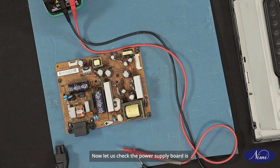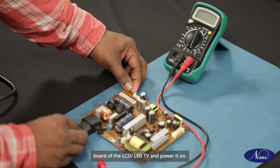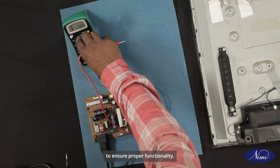Now let us check if the power supply board is working using a multimeter. So examine the description near the connector of the cable leading to the LCD or LED TV. Ensure that the voltage indicated matches the required specifications for the TV. The same voltage should be visible at the end of the cable when checked. Connect the AC socket to the power supply board of the LCD or LED TV and power it on. Carefully explore and test various voltages to ensure proper functionality.